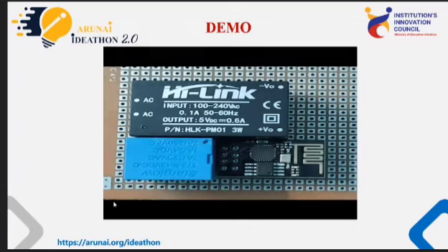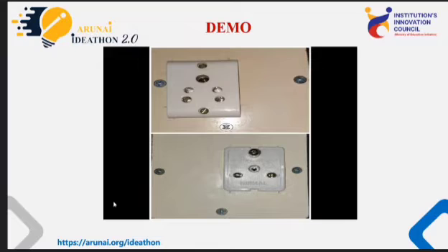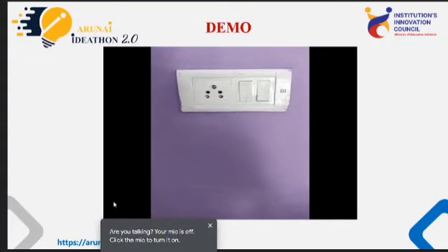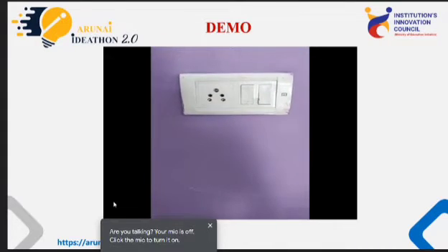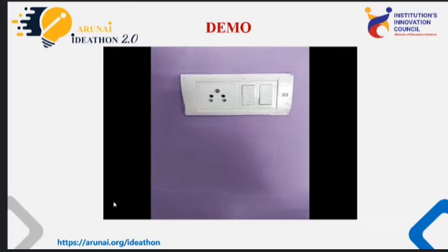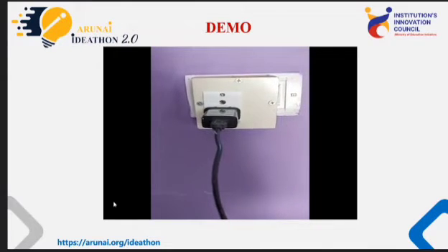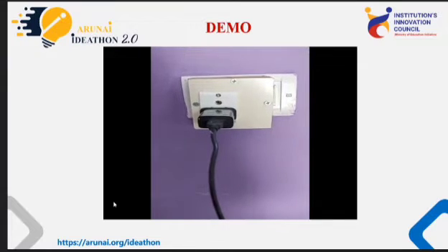With the help of soldering, we connect the relay module, AC to DC converter, and the resistors, using electric wires and inserting them into the small socket which we made. This is the normal household socket. When we forget to switch it off, there is a lot of energy loss. To solve the problem, we can replace the normal household socket with a smart socket.